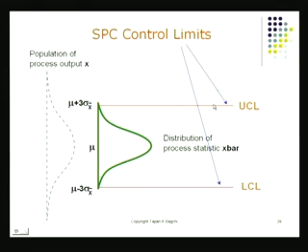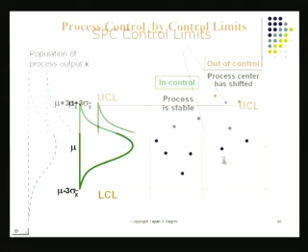So, the control limits actually turn out to be narrower than specification limits. The process variation is going to be much wider by itself, raw process variation. But the process variation in which we've got interest is the variation of the x bar quantity or the range quantity, and that's got to stay within these control limits. So, I must use the formula for UCL, I must use the formula for LCL to know exactly what this range is, where if x bar values lie within this limit, of course, I've got no anxiety at all.